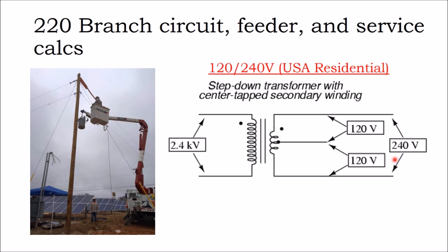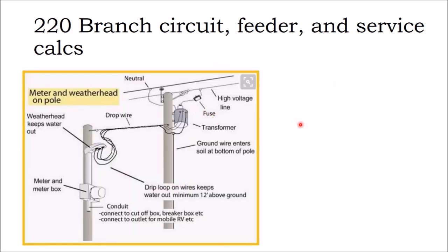In other words, you have a leg 1 and leg 2 of power on a residential service, and that goes all the way up to the box on the rooftop, whereas most of your power outlets are 120 volts, and they're just stacked on either side of the service in somewhat of a balanced process. So the transformer is taking our utility distribution voltage and stepping it down to stuff that our home can use.